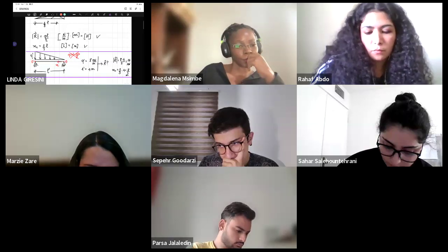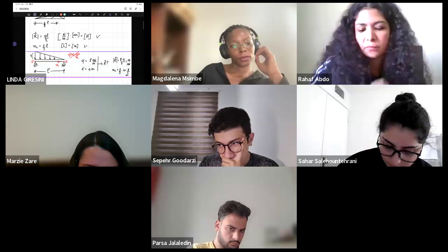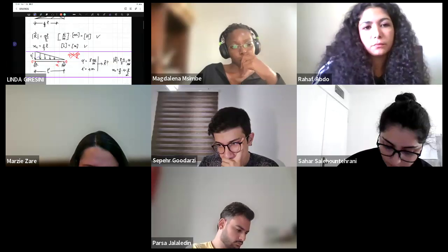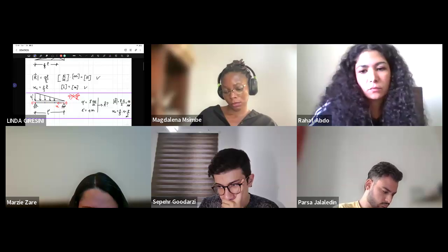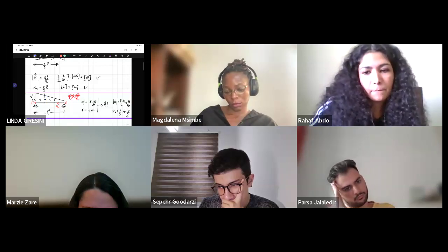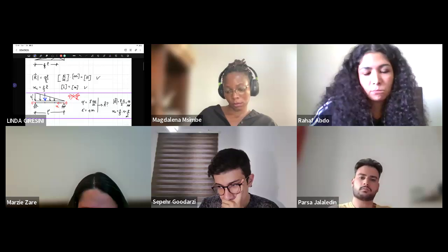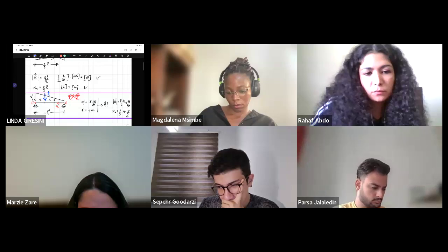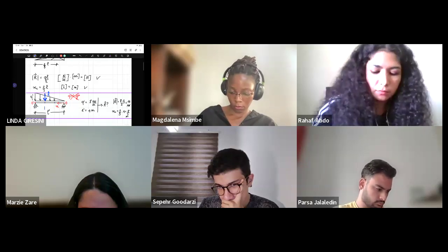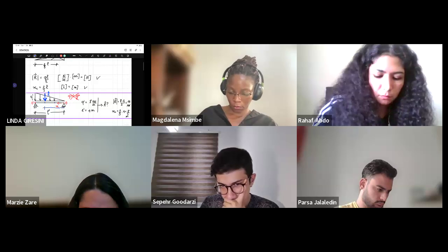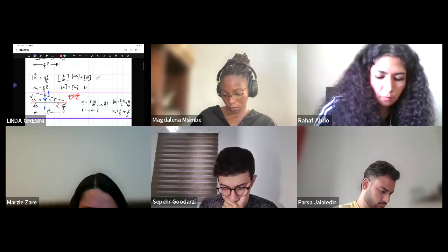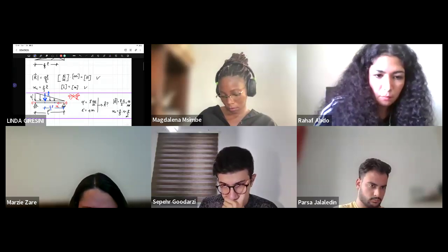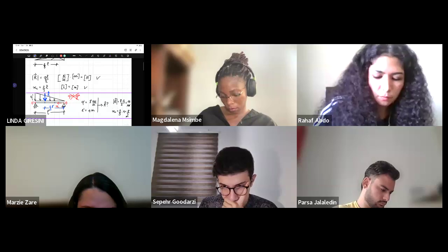So it will be somewhere here. Basically, you can divide it by 3. So this is 1, 2, 3, and you take 2/3. So this will be the precise point of application of your resultant. This will be at 2/3 of L first. Okay?